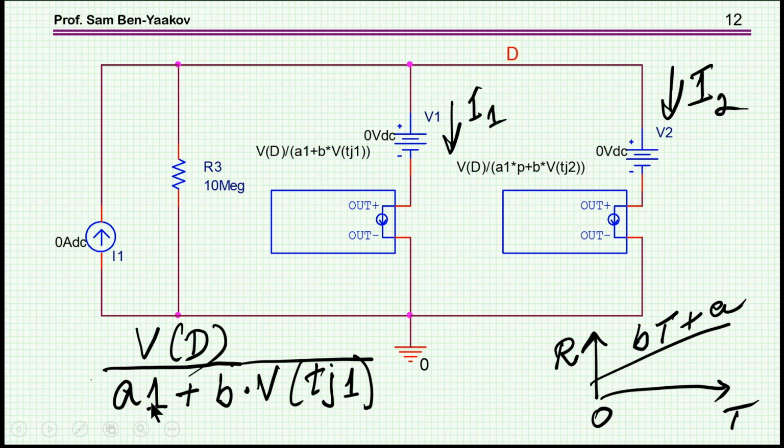These are constants, which are defined in a parameter list, I'll show in a minute, times the temperature of the junction. The temperature of the junction here is coded into a voltage. That is, later on you'll see a node that has a voltage representing the temperature of the junction. So this is now the resistance RDS(on), and this current source represents this resistance, and of course I'm approximating the RDS(on) by this straight line.